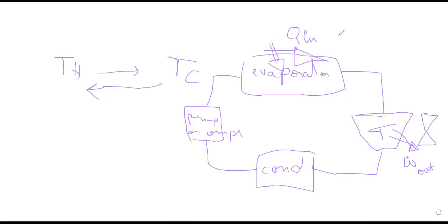The internal energy of it will increase. Once it reaches enough energy level, it will get out of your evaporator and pass through the turbine. In the turbine, as we discussed a while ago, the enthalpy, which represents the energy carried by this fluid plus the effect of pressure, will be transformed into work, because the enthalpy will decrease as you go through the turbine and you will release energy in the form of work to the outer environment. So you are producing work.